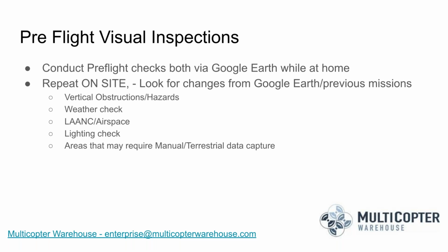And yeah, the data from the Mavic 2 Enterprise Dual, you won't be able to get that processed through Pix4D for mapping purposes. The resolution of the Mavic 2 Enterprise Dual camera is just really, really low. It's 160 by 120. Yeah, it's more for qualitative assessment. Yeah, hot, cold, good, bad, but not really quantitative of different degrees.